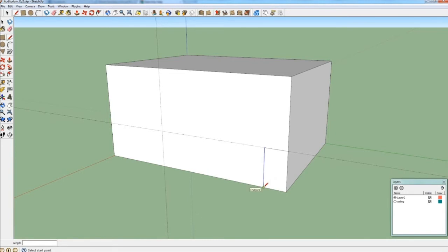And now I also draw another line from this point to the end of the stairs, and I do the same thing for this line. And now I take the number of segments, which should be 20, and I see that the length of each tread should be 0.44 meters.